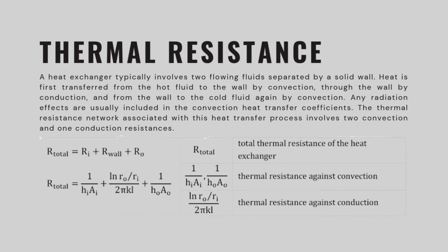In the analysis of heat exchangers, it is convenient to combine all the thermal resistances in the path of the heat flow from the hot fluid to the cold one into a single resistance, and to express the rate of heat transfer between the two fluids as a single quantity.